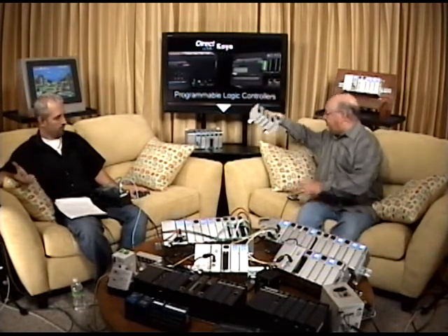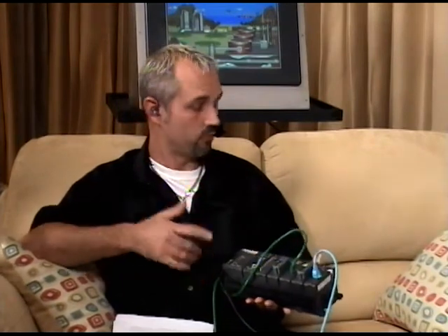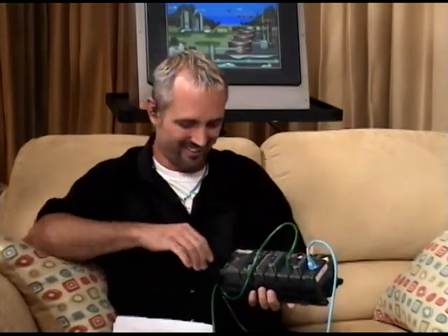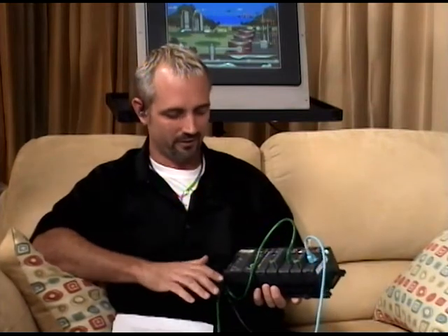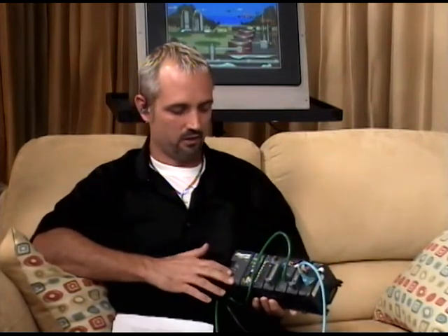Okay, HMI to PLC communications, there again, Ethernet. What's nice about that is just a quick example. We've got a 260 CPU in this 205. Well, if we were using serial communications to a touch panel, like the one behind my head back there, which looks like a window, then you're going to take up one of your ports, right? So that leaves you one port for the HMI, and one port for communicating to your computer for programming.